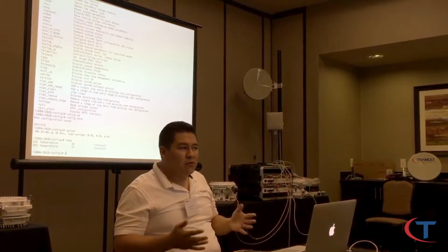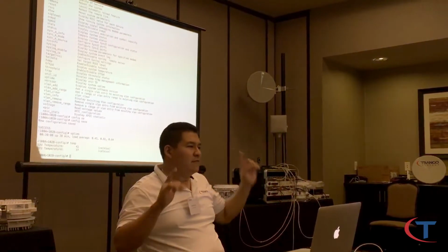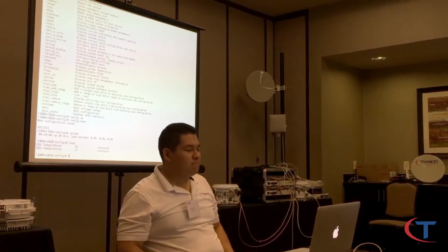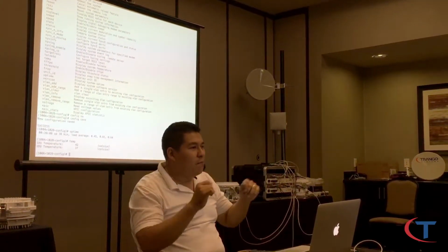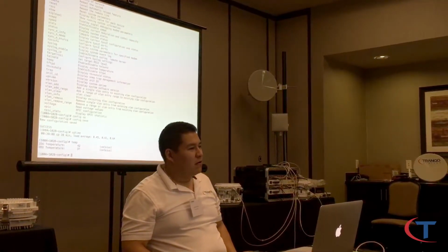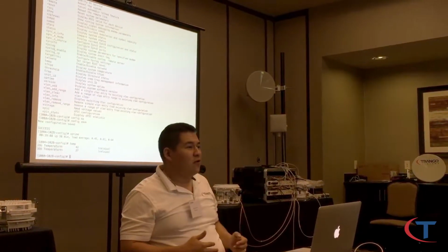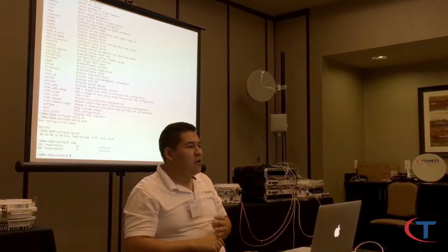I was kind of, well, why did it unlock on me? I started a little more troubleshooting. After a couple hours, it unlocked again. I said, okay, I know what the problem is. It's my far side transmitter. Has to be bad. The ODU has to be bad. I go up to Black with another ODU, swap it out, same thing happens. Wow. So I take a look at the inside of the ODU. With my privileged user from Triangle, I can see everything is fine. Receive signal, power coming out, but it still unlocks on me.